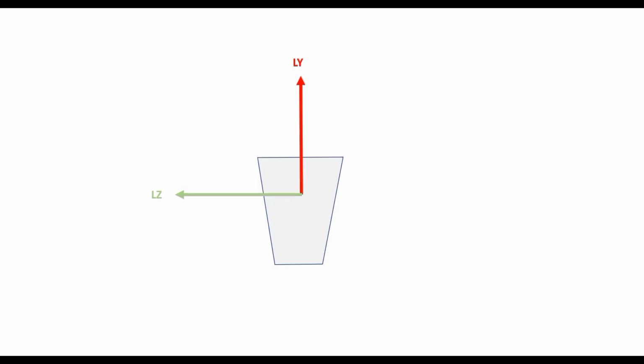The trapezoidal section can be defined by three parameters: the larger width of the parallel sides, ZD, and then the smaller width of the parallel sides, ZB, and then the depth of the trapezoid measured as the distance between the parallel lines, YD. Now, ZD and ZB, I had explained that as the larger and the smaller sides of the trapezoid respectively. However, the larger and smaller are relative terms.